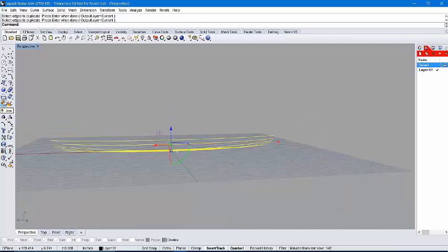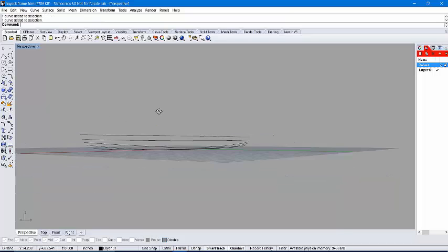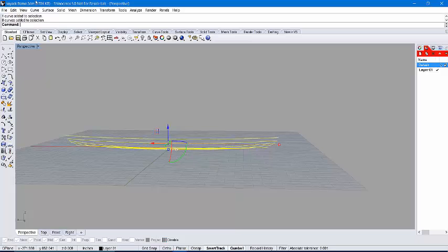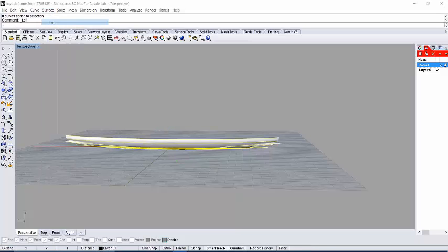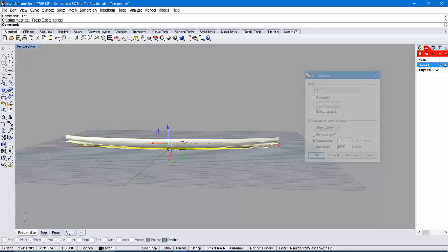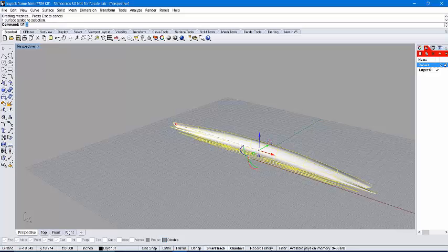So now that I have all my guide curves, I am going to create the guide surface. And the way to do this from these curves is just to highlight them all, go to Surface and Loft. Now when you're doing this, Scan&Solve Pro can only read NURBS curves. They cannot read a poly curve. So to do a loft, you need to make sure that you have the uniform option set up, as well as the rebuild option checked. And when you click OK, it will create the surface for you. And just to make sure that it is a NURBS surface, I can hit What, and you can see here, NURBS surface, and this is what we want.